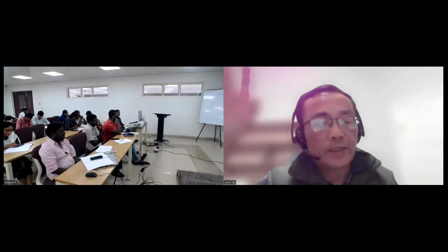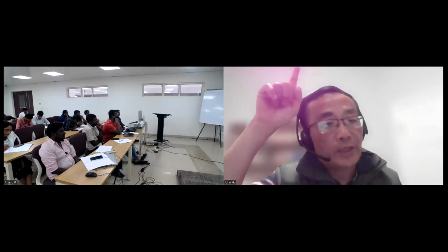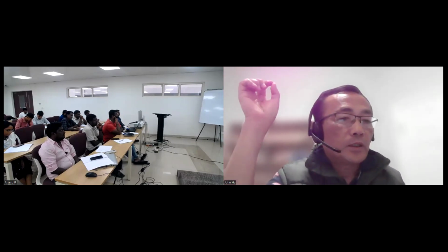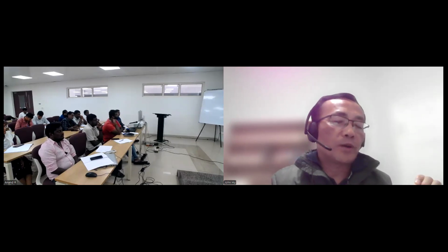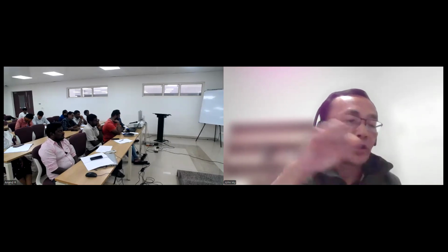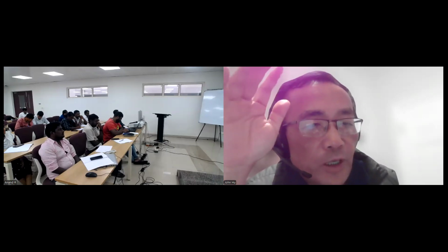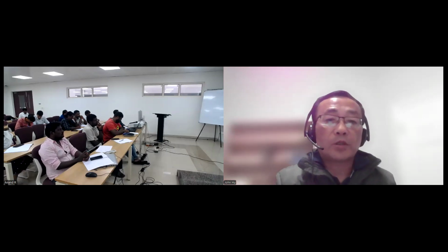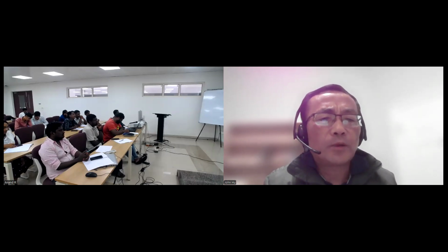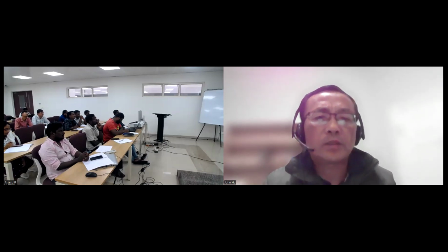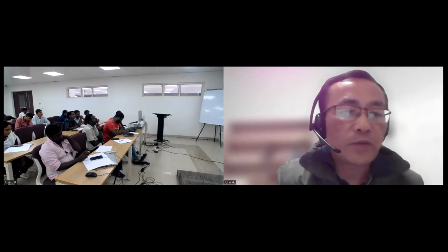So there will be a curve kinetically. You use kinetics to calculate the specific activity, not the laboratory specific activity. That means you have the laboratory specific activity and the kinetics, and you use the kinetic curve to predict the specific activity at a larger scale. Okay, so that's the engineering calculation. But for an exercise like today, linear calculation is good enough. That's what I wanted to show you, because when I read this paper I saw 1.2 ton per 400 kg and thought something was wrong. Now when we went through the calculation, we even got a larger number.